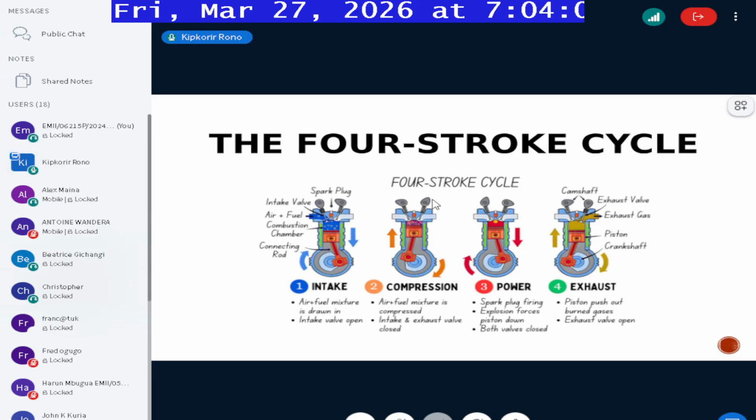So in those conditions, usually there's something known as a distributor that is synchronized with the movement of the cam, because the cam is what controls. You can see there's the camshaft. So the camshaft, which has the cams, is synchronized together with the distributor.